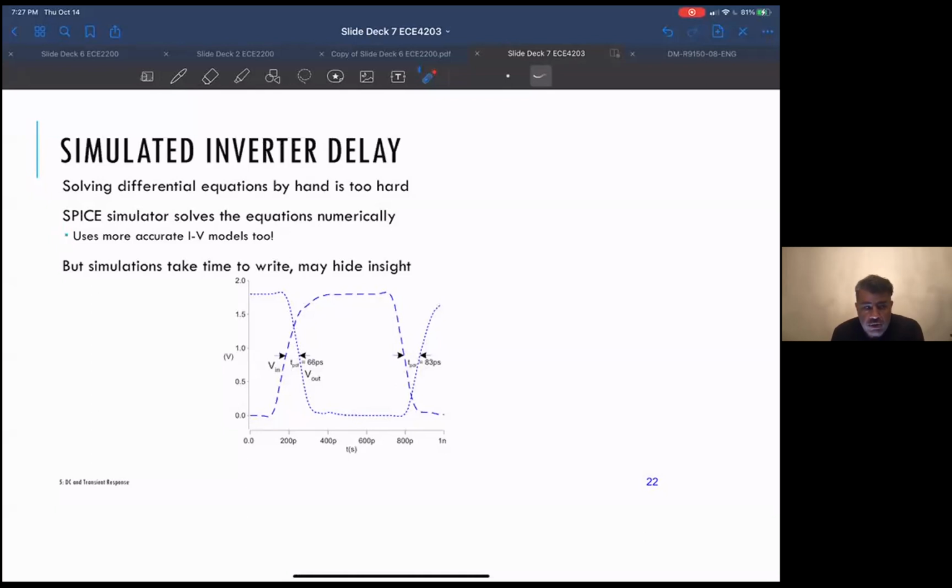So to actually get the delay of a circuit you're designing, so this is the circuit, okay? In this case, it's just an inverter. You put it together and you actually simulate in SPICE, and that's as accurate as you're going to get, right? We're doing that in parallel, but the methodology that we're going to talk about now is intended to get us a rough order of magnitude or an estimate of the delay.